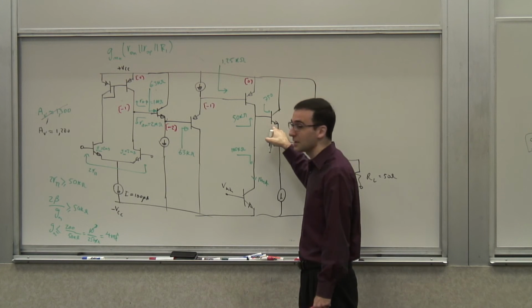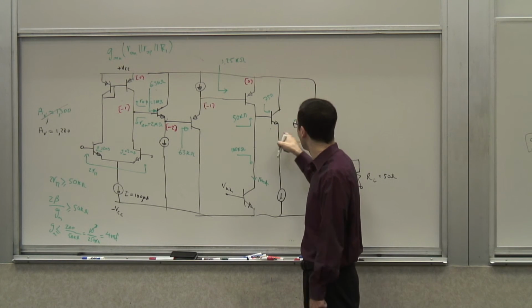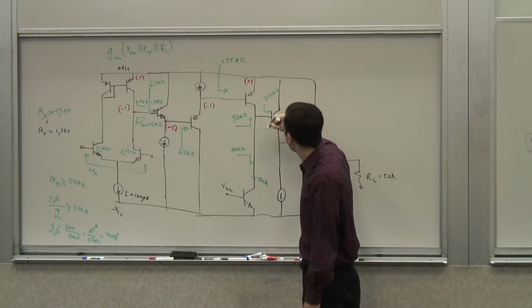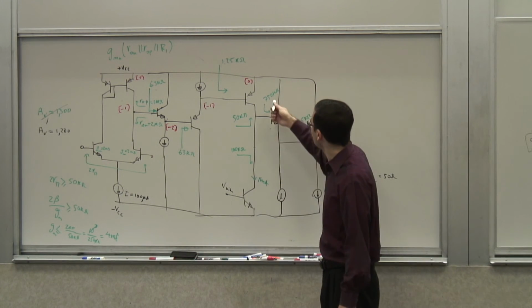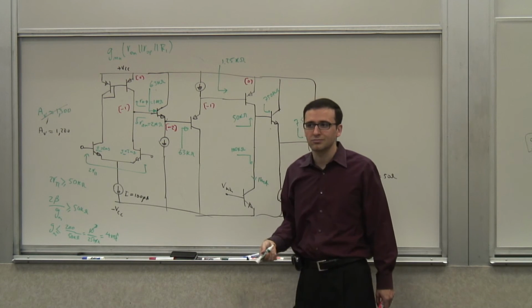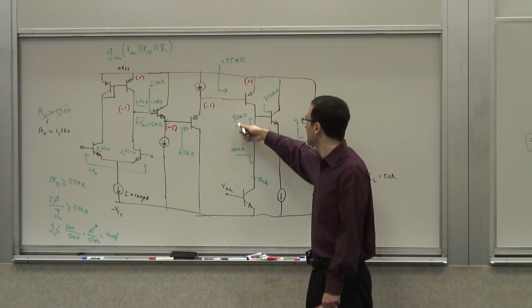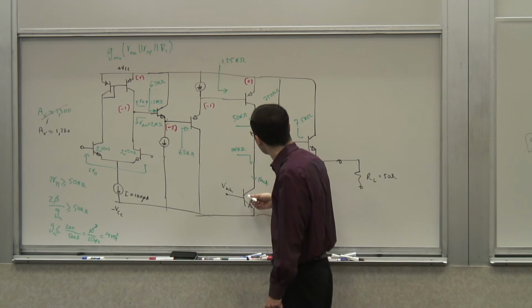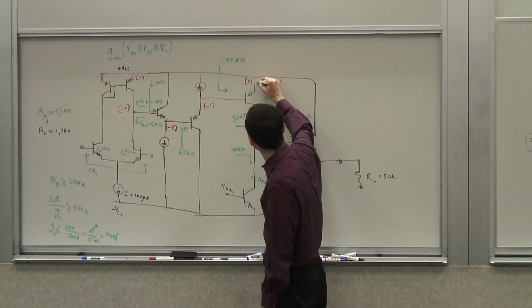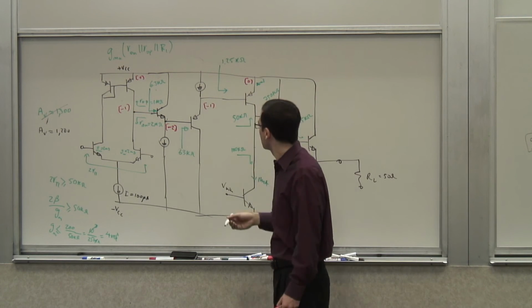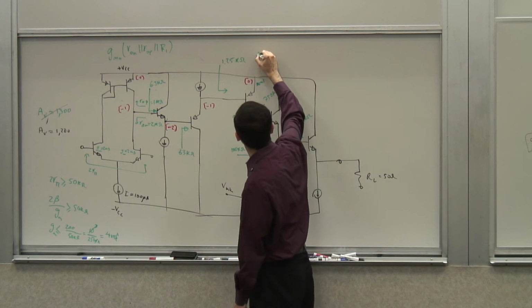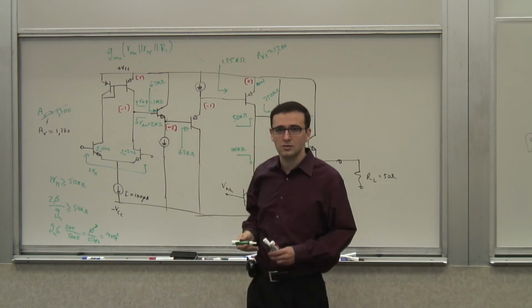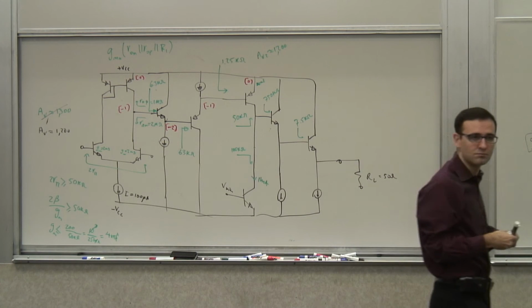This time I don't have to worry about this Rn, right? Because it's 7.5 kilo ohms plus 25 ohms, kilo ohms approximately. So that's okay, right? 750 is reasonably higher than these 2, so that probably makes that 33 kilo ohm, 30 kilo ohms approximately. So 30 kilo ohms times the GM of this guy, which was 40 millisiemens. 40 times 30 is 1200 approximately. So 82 is approximately 1200. So it's 1200 times 1200, so okay, so 1.4 mega